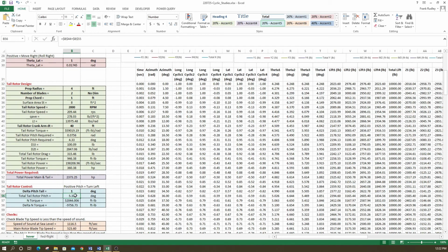Well, it added more pitch, so it causes counterclockwise. So it turns the body counterclockwise. So I needed, on top of the 4.33, it added 1 degree. I didn't go back in and figure out the additional drag I would get, because that would take more power.